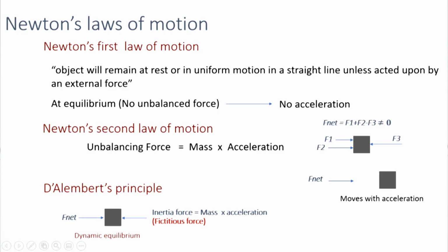The only difference is that in addition to the applied force, we have to consider this inertia force also. So this is an additional force which we need to consider in dynamic analysis. And this fictitious force is called inertia force.